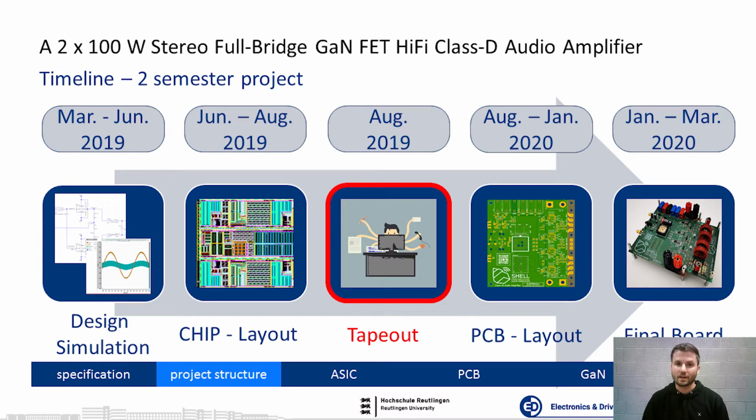In the first half of the project, we defined the system's architecture and set up top-level simulations to verify the basic delta sigma modulation principle. After verification, we designed our ASIC using Cadence tools and commercial semiconductor fabrication processes provided by X-Fab in Germany. Particularly exhausting to comply with was the tape-out deadline, which was dated right after our exams and extended our term.